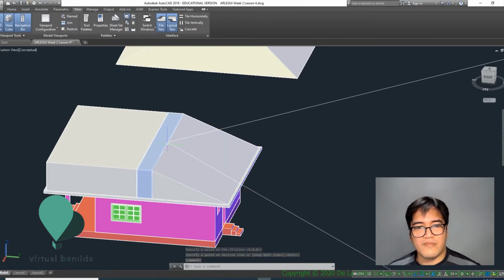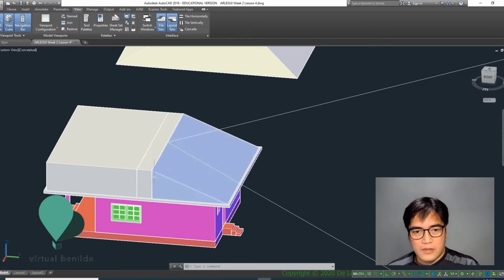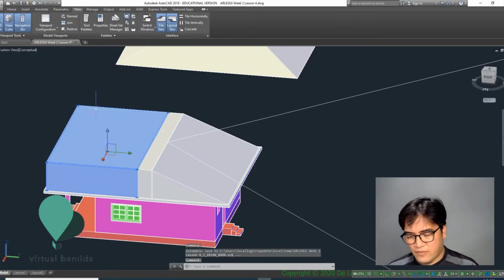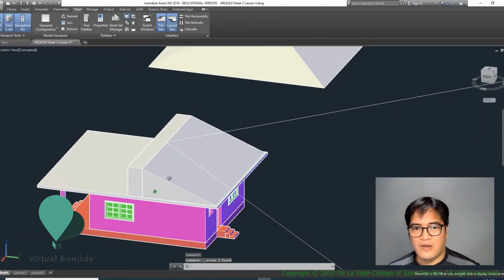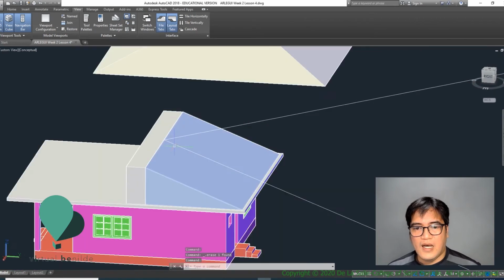So I'm going to cut from the 3 points. I want to cut this plane here, right here. Okay, let me just show you that. So I'm gonna leave these. I'm gonna slice these 2 objects. Actually, this one on the other half, you don't need it anymore, which you will see later on in the video. I'll erase that eventually. All right. So I'm gonna slice these 2. SL. Choose these 2 objects.